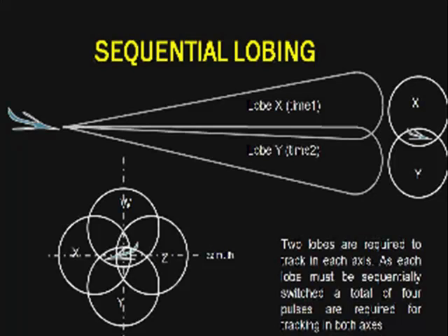That means, as shown in the diagram, if you have four lobe positions A, B, C and D, you can get the angle informations azimuth from C and D beams, elevation from A and B beams.